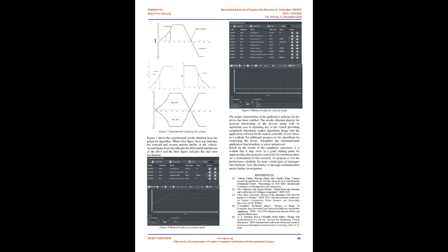C. System architecture. This section presents the design of the motion controller system. Figure 2 demonstrates the overview of the system. D. System functionality. The system schematic includes a control unit and electric motors. Software for controlling motors includes multiple tasks, where specifying the baud rate and node ID is a one-time process which is set using the respective motor drive software. The motor drives inherently assign higher priority levels to the CAN tasks. One of the important tasks is to make sure that the devices have not entered into any of the error states. The factors for controlling the motors depend on the input received from the Bluetooth device, which can also be altered based on the requirements.